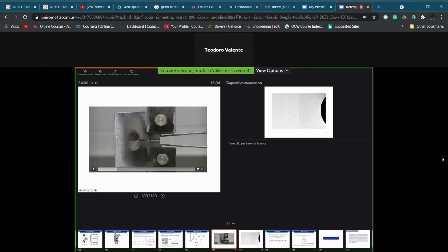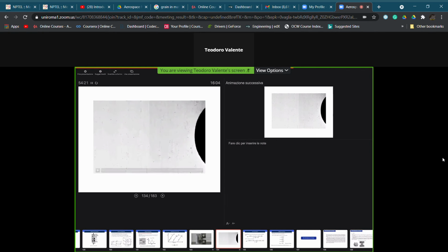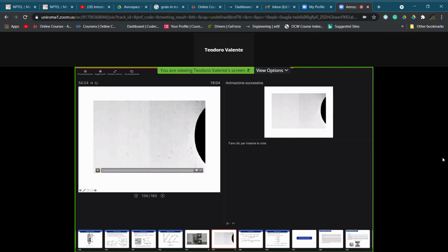This is the extensometer, the device which is used to evaluate and record the displacement depending on the applied force. And this is another example of propagation. You see here, we do not have any defects. We are inside, in this special case, an aluminum alloy, which is subjected to fatigue on a CT specimen. Have a look here at how fatigue can generate a pre-existing crack.